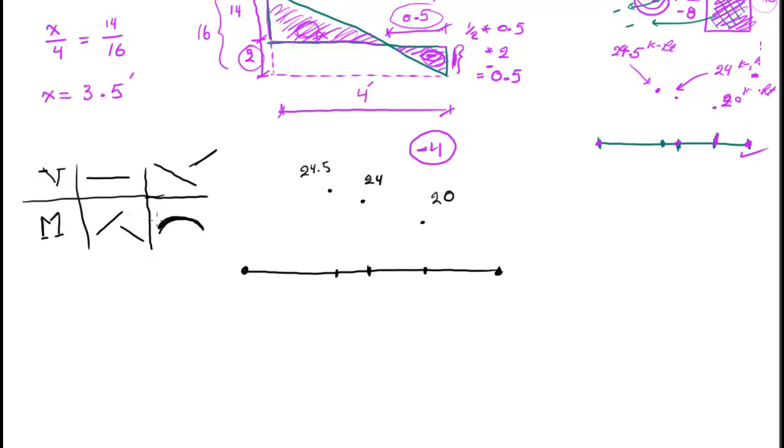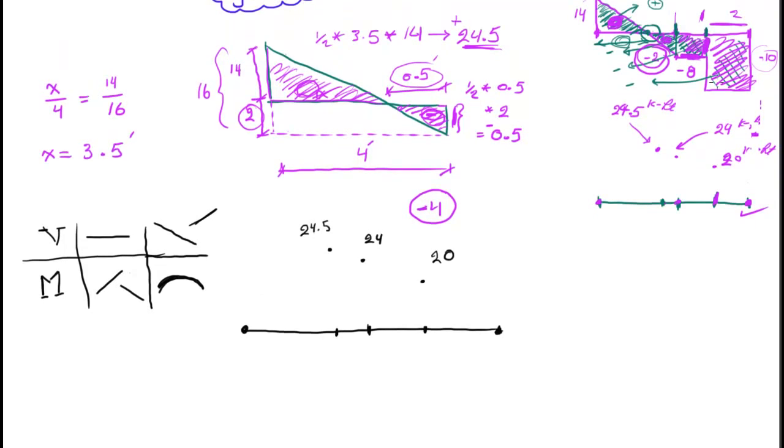So let's apply these rules. It's very quick. From this point right here to this point, I have a straight line, but it's declining, so I'm in this category. What should I get? A parabolic curve. So from here to here is going to be something like this. It's not a straight line. Now between this point and this point I have a horizontal straight line, so I'm going to have a straight line. And from this one, I'm sorry, this one's wrong, forgive me.